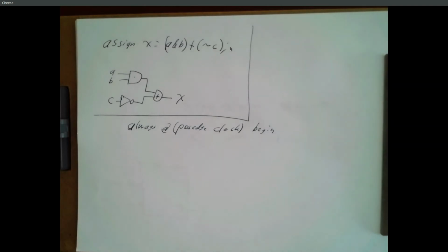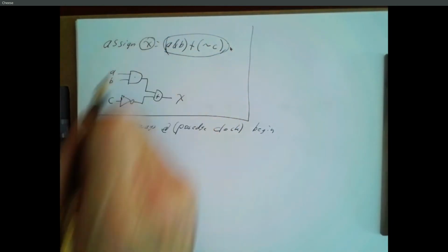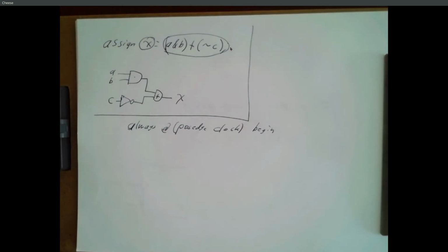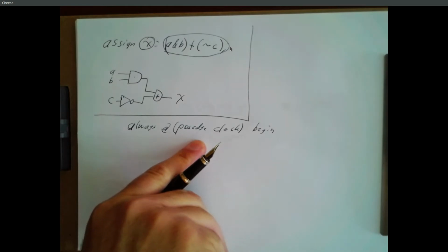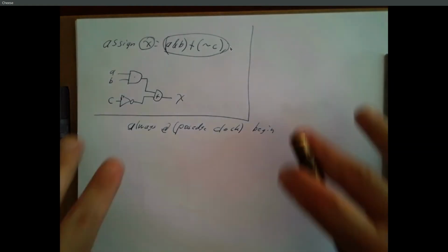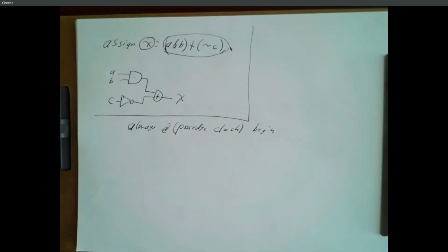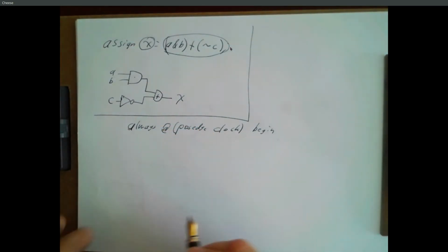And we can't really do an assign statement inside an always block. Because remember, assign is saying build this, connect its output to this. And if we put an assign statement inside an always block, we're saying whenever the clock ticks, I want you to build a circuit. I want you to connect this to this with a wire. And the way Verilog is written, it doesn't let you actually modify the circuit while things are running, right? It's describing a static picture of a circuit, right? I'm working on changing that. That's another story. So we can't use an assign statement, but we can do something like this.